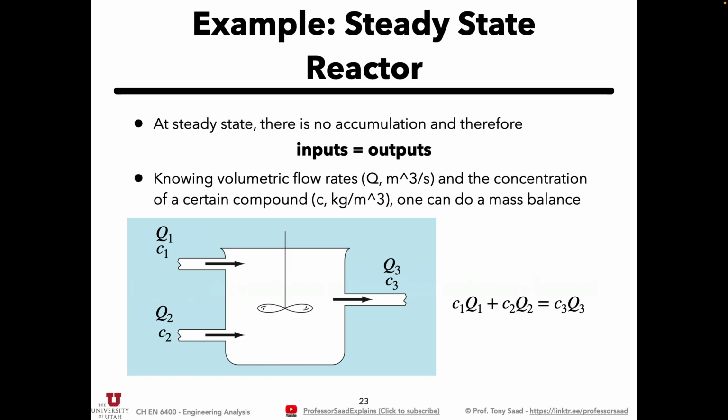So when you're thinking mass conservation, you immediately have to think kilogram per second. It's mass per second, mass per unit time. So when I multiply flow rate in cubic meters per second times concentration in kilograms per cubic meter, I get kilograms per second. So that gives me whatever mass is coming in from this pipe. There's another mass that's coming in from this pipe. It could be a different flow rate and a different concentration. They're getting mixed somehow.